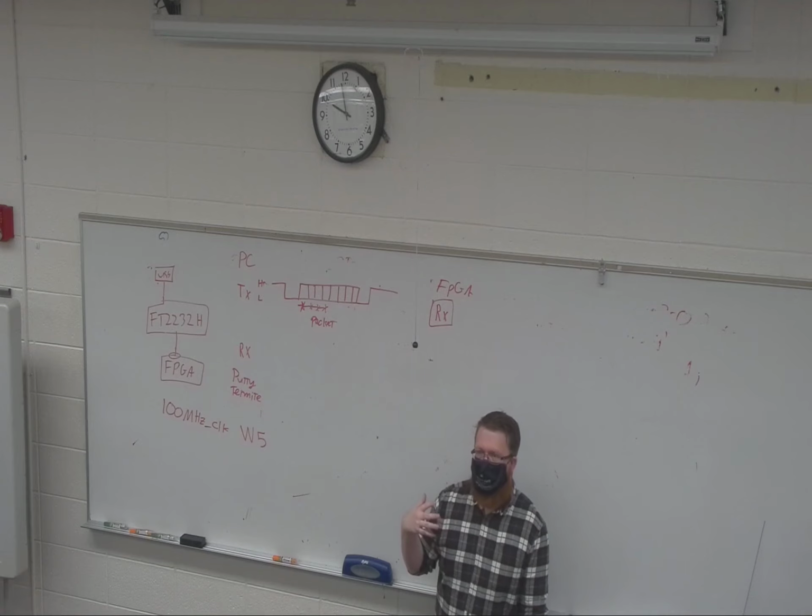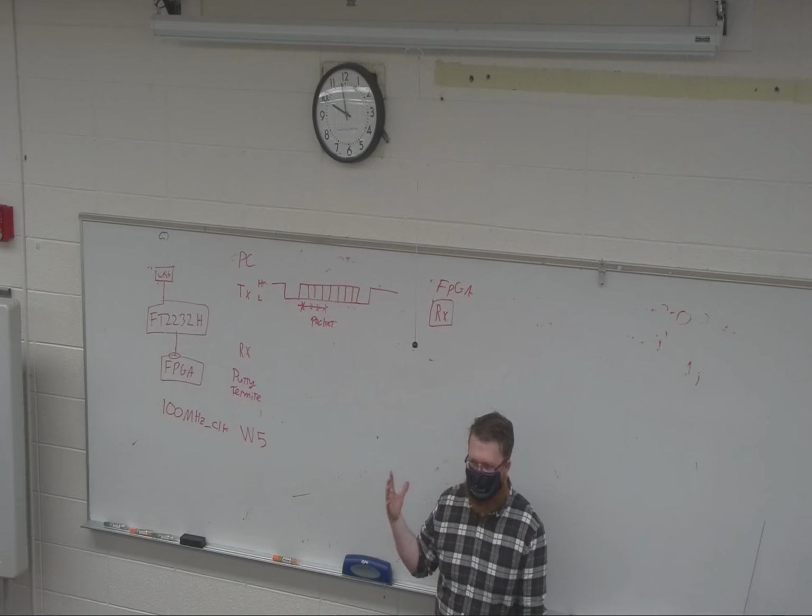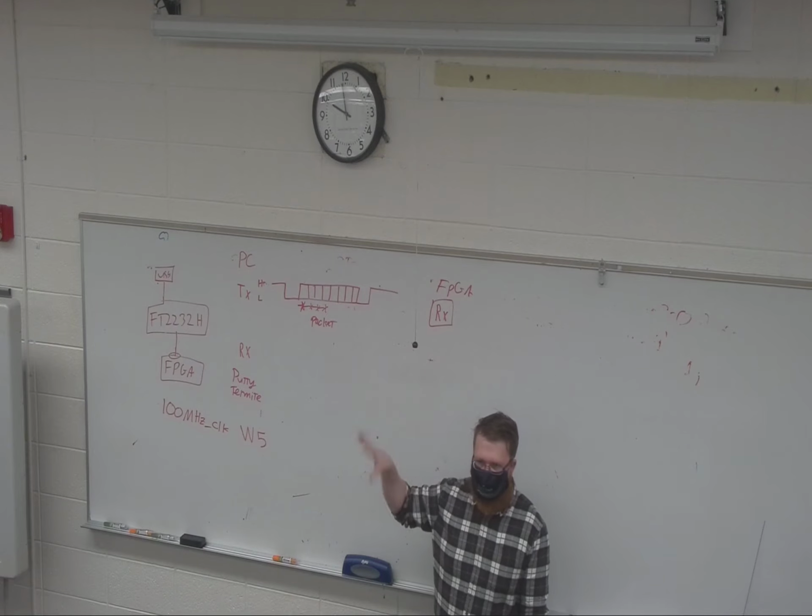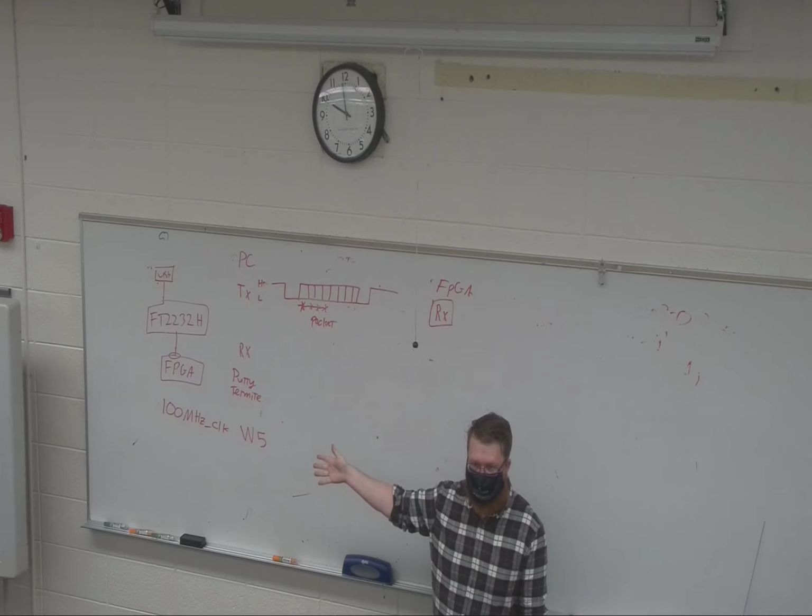and you're going to see if you get the data bits. I will show you how, either in here or in the lab, one of the two, how to write a test bench. They're really not very difficult, which is very fortunate. But you're just going to simulate signals going into it, and your state machine is going to pull data from it and load it into some buffer, which you can then do something with.